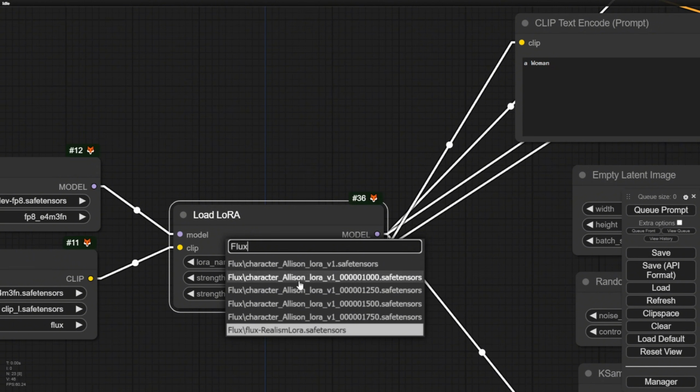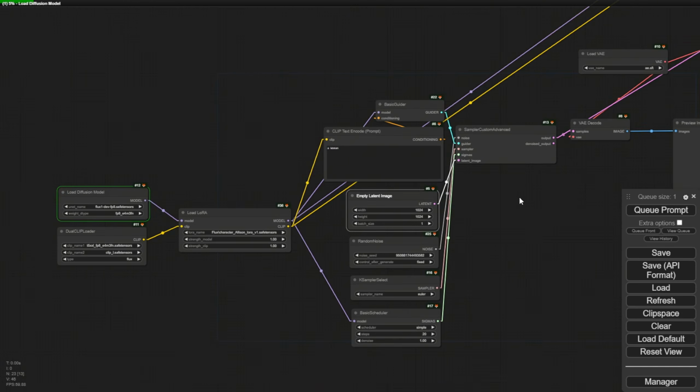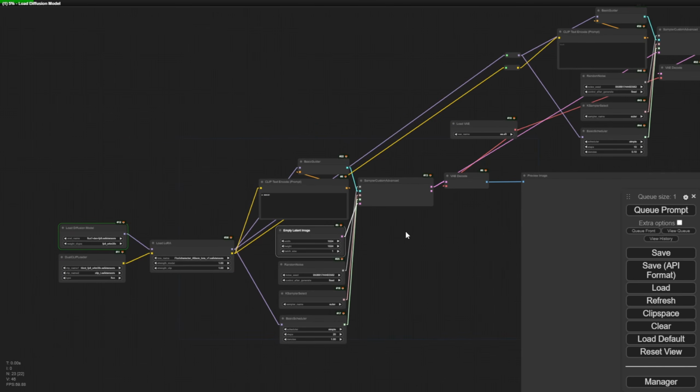So whichever one you select, you can try the generated LoRA in ComfyUI. With a very simple prompt, I just type my trigger word. Then let's see what I have in the output. I have two sampling custom node groups. The first one is going to generate from the empty latent image, and then the second one is going to be the image to image that's based on this first latent image. We'll see if there's any difference between the two samplings.